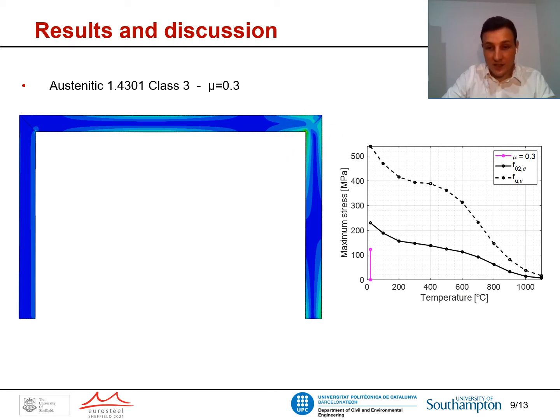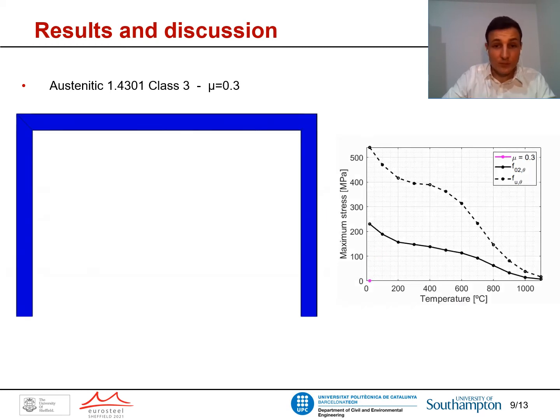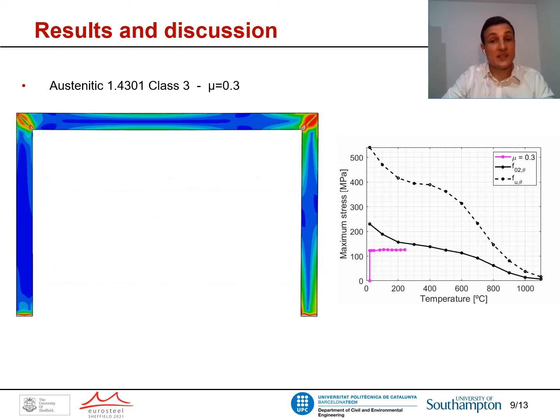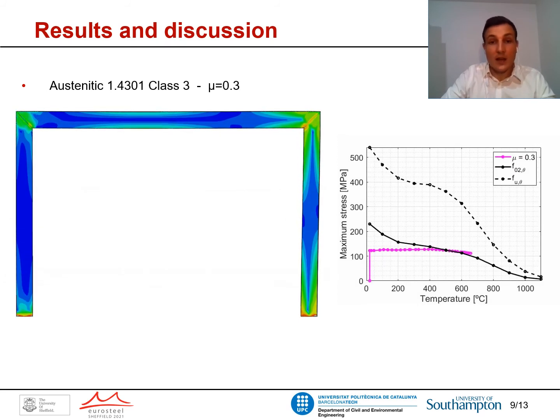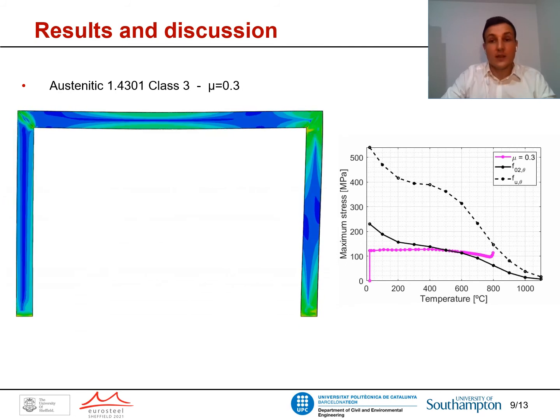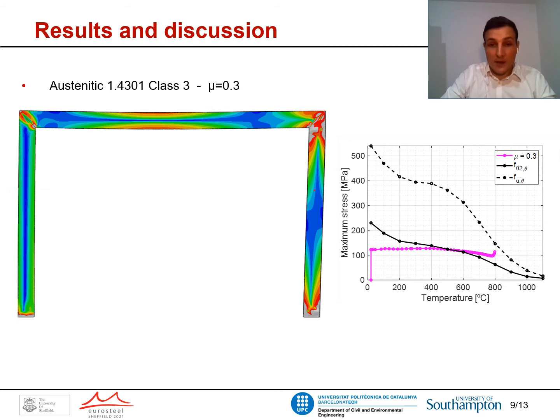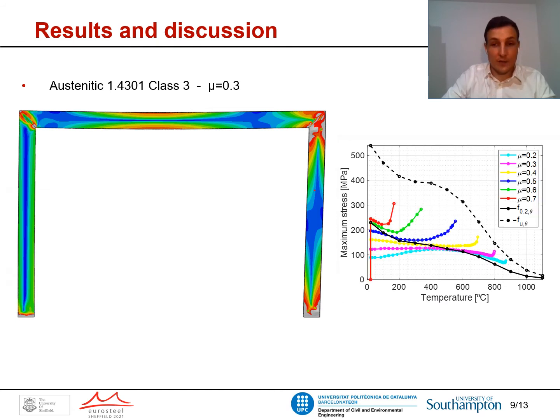Now it can be seen an initial stress due to the load already applied before the fire starts. Once the fire starts, the frame starts to expand due to thermal dilatation. Then the stresses start to develop, and after surpassing the yield stress, the frame collapses. The frame fails due to local buckling after surpassing the yield stress, as expected. All other Class 3 frames analyzed under different degrees of utilization fail, describing a similar behavior.